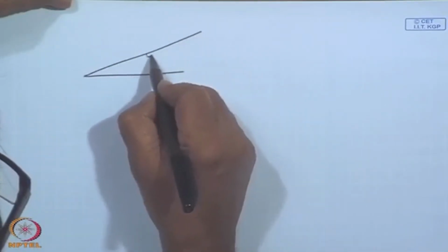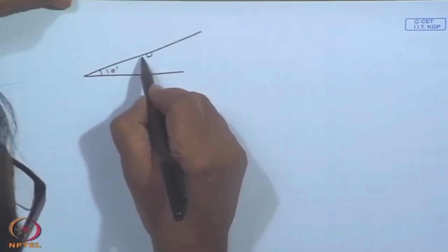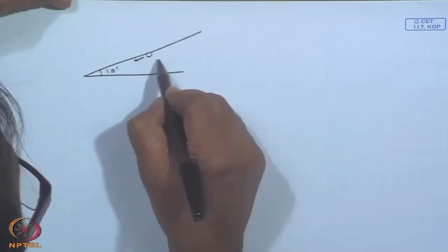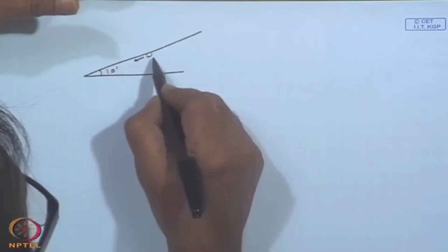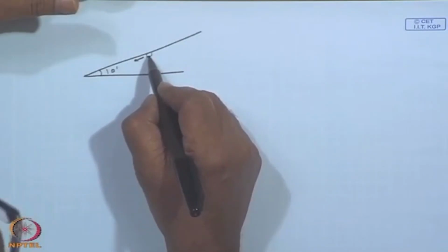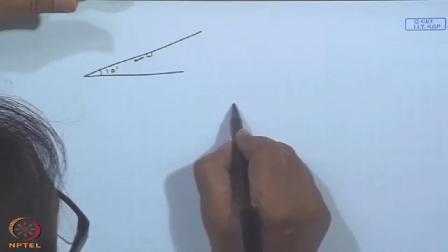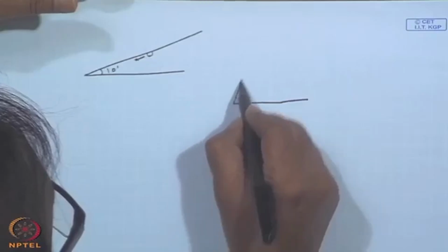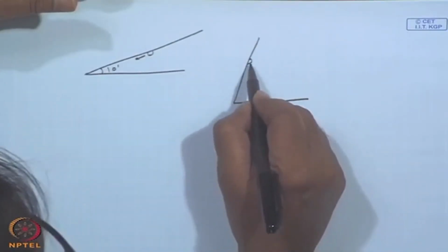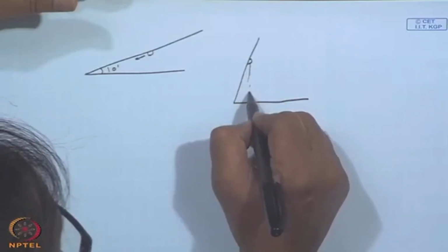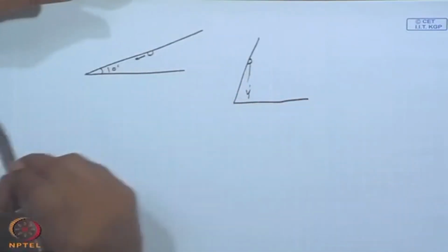So, this is what is going to happen, and then this angle, if you find a drop, it tries to come this side because of gravity, right, some component in the vertical direction, and it tries to stick to this because of surface tension. And if you have too large an angle, it may come down straight and not flow along the surface.